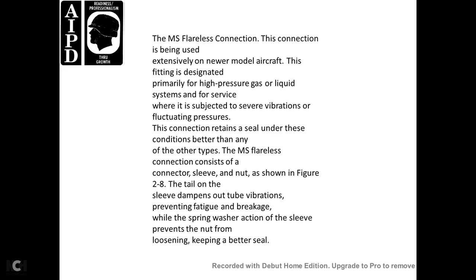Military standard flareless connection. This connection is being used extensively on new model aircraft. The fitting is designed primarily for high-pressure gas and liquid systems where the surface is subjected to severe vibration and fluctuating pressures. The connection retains the seal under these conditions better than any of the other connections.